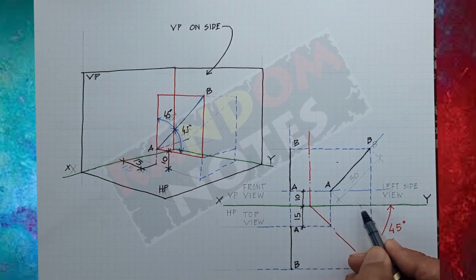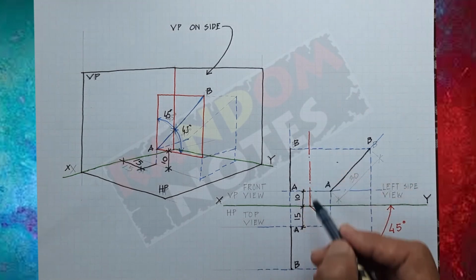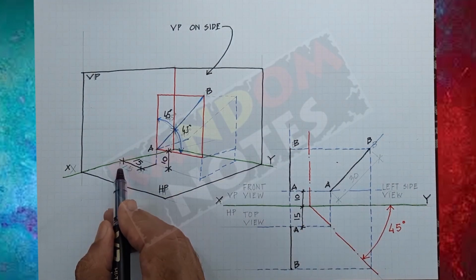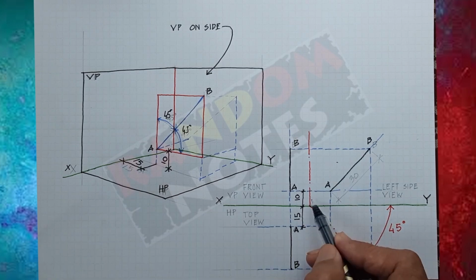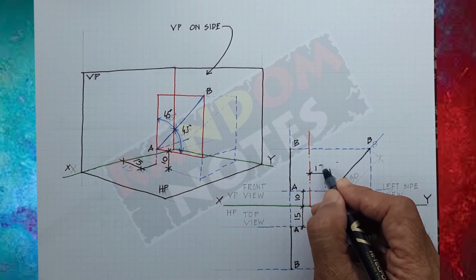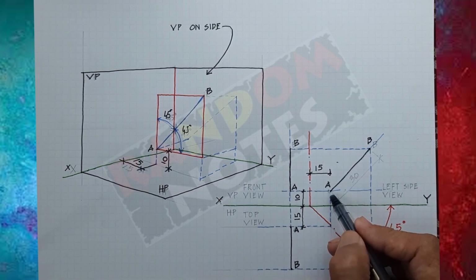So from the XY line at a distance of 10 mm we'll get this point, and this red line is the line of fold. From the line of fold it is at 15 mm distance, so that 15 mm distance will come here. So 15 mm from here, 10 mm above this we got point A.